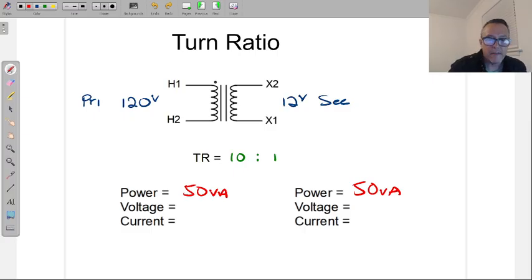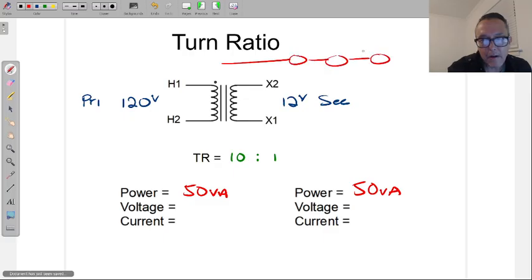The transformer is able to handle up to 50 watts connected to it. If you connect something to this transformer that produces 100 watts when you turn it on, you're going to fry this transformer. All right, it'll just get heated up too much and it'll break. That's why I say you buy the transformer based off of the wattage demand. So if, for example, we're hooking up a bunch of LED lights outside of a building, wherever, doesn't matter, and each one of the LED lights are 5 watts each, then we can put 10 on this particular small transformer.